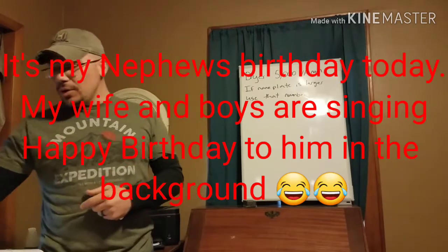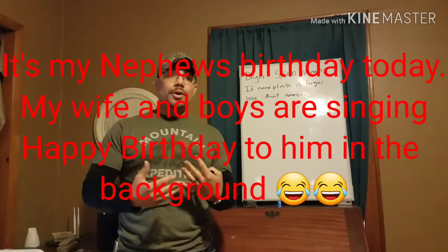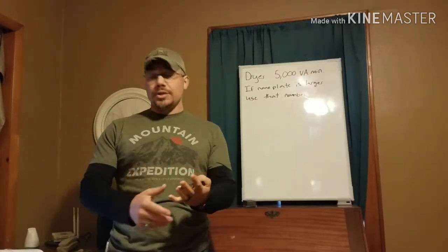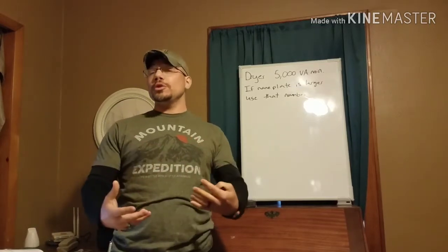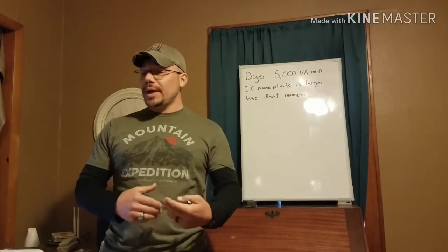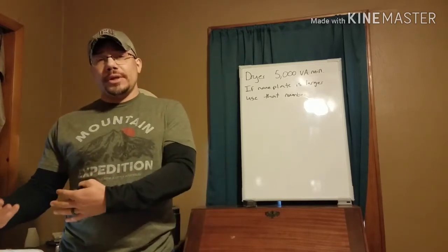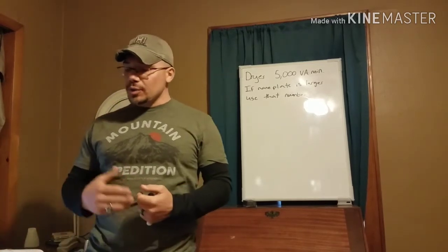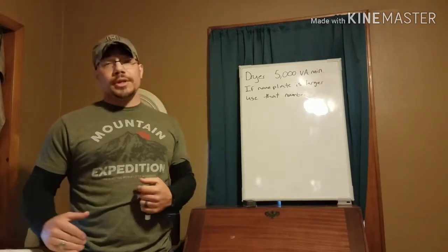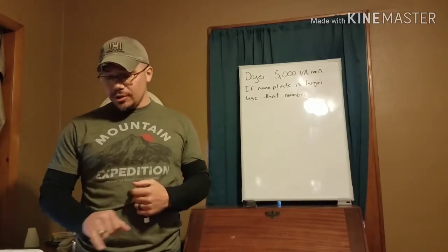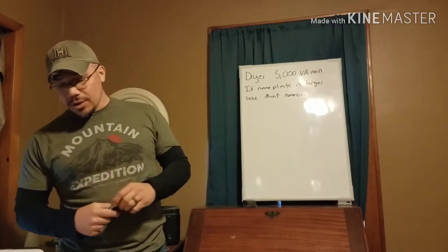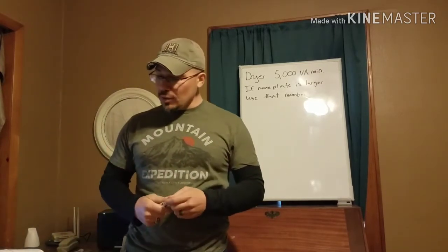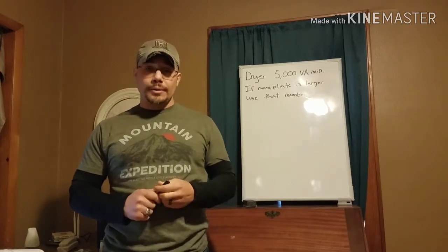So what we need to do is first figure out whether this is one circuit we're dealing with, or if it's going to be multiple different circuits, and then how much those circuits are going to be. So we're going to look below this table. If you look below the table, you're going to see there's Note 1, 2, 3, and 4. Note 1 says over 12 kilowatt through 27 kilowatt of range is all the same rating.